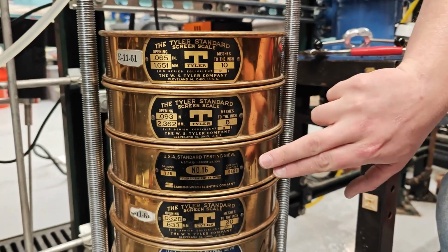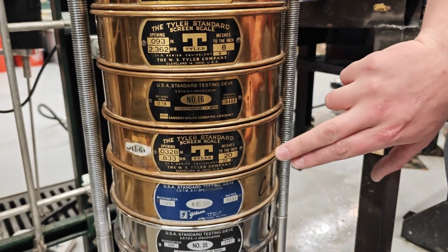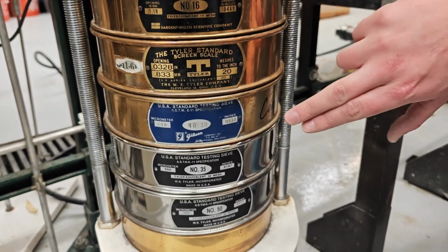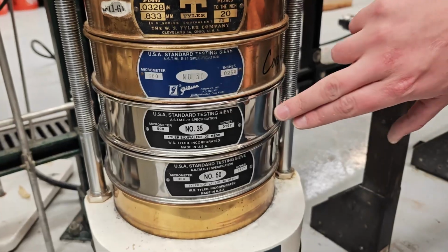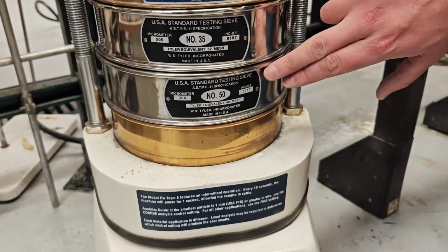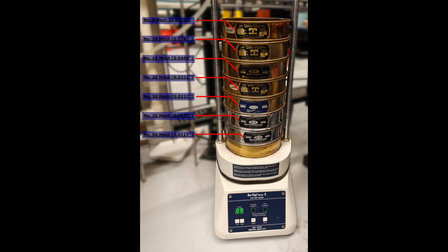It's the sieve machine. The sieve machine has different tray sizes to allow for the distribution to be created. These can be seen more clearly in the following diagram. The different trays have mesh in them, which allowed particles of different sizes to get through. This is how we can create the particle distribution. The largest sieve tray we used was a number 8 mesh, which has an opening of approximately 2.4 millimeters. And then the smallest we used was a number 50 mesh, which has an opening of approximately 300 microns.